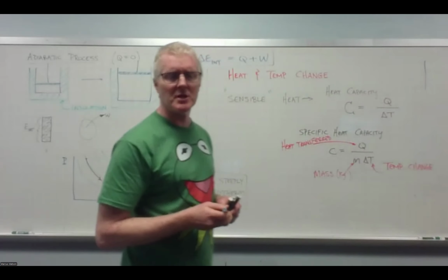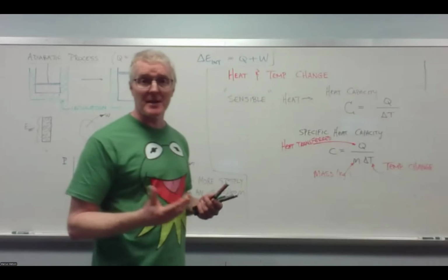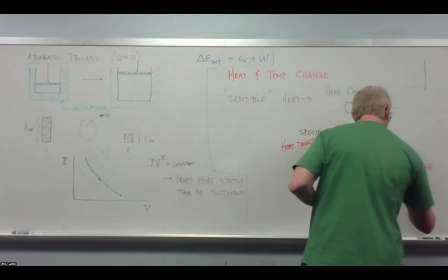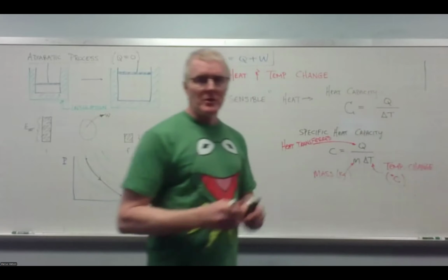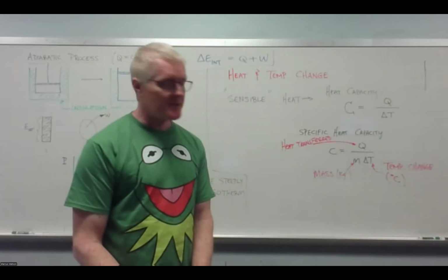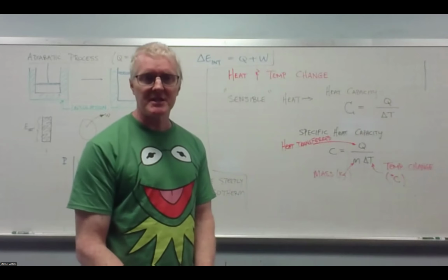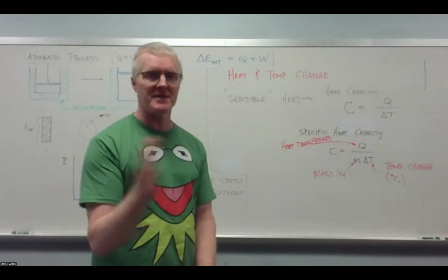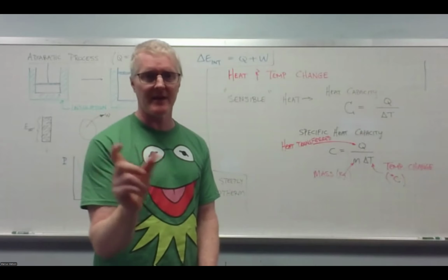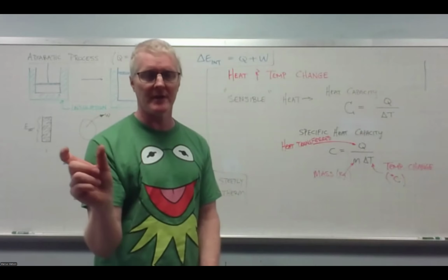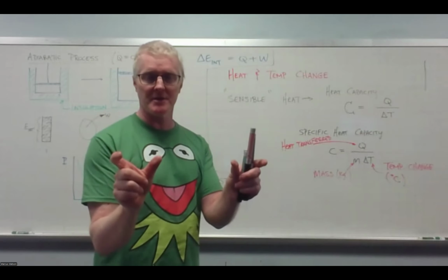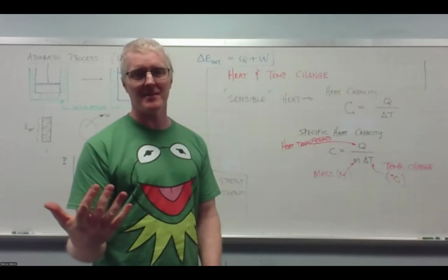The temperature change, now since this is a temperature change, we can use centigrade. You are certainly welcome to use kelvins for this. Delta T in Kelvin is exactly the same as delta T in centigrade because they're just offset by a constant value, right? So no matter what you are on the Kelvin scale, 100 is the same as 100 on the centigrade scale. Now, it's not the same on the Fahrenheit.